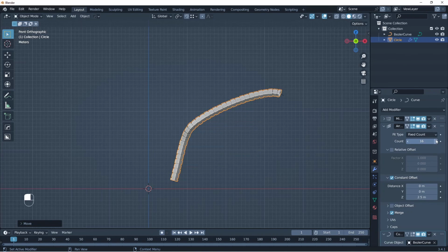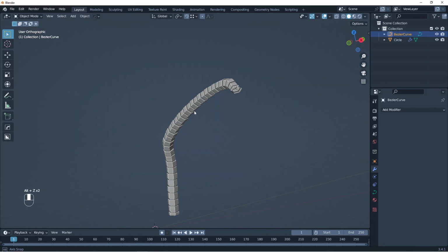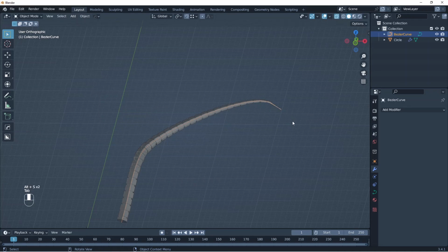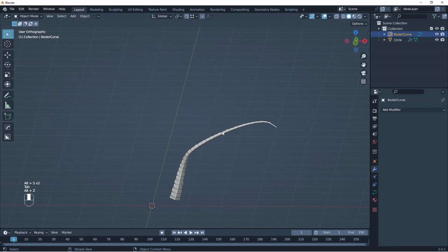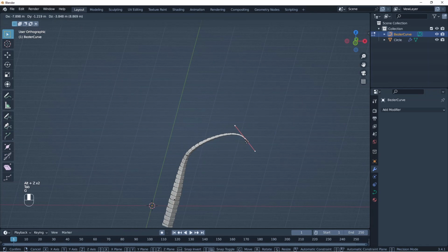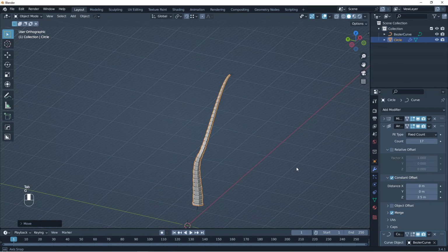So to avoid all of that, we do it from the middle, but that's the way to actually fix that. To finish this, we need to make it smaller on these last parts. So we go to the curve in edit mode and press Alt S, and that's going to make this one thinner or thicker. And also here, maybe we can make this one thicker, you see. If you also move it in edit mode, you can just keep adjusting this, it's pretty cool.